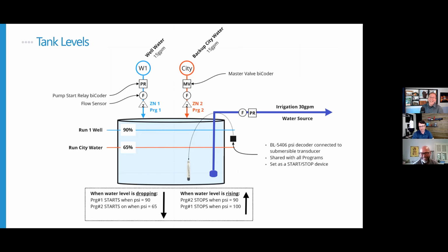Yeah, how about 1 year ago when we were using soil moisture sensors in tanks, which is still a great way to do it. But a soil moisture sensor or any mechanical sensor basically tells you there's water or there's not water, but it doesn't tell you a scalable how much water. So if you're listening to this and you've used one of our moisture sensors in a tank, you may have put it at the bottom of the tank, and if the tank goes dry, we will pick up that dry signal and turn off irrigation.